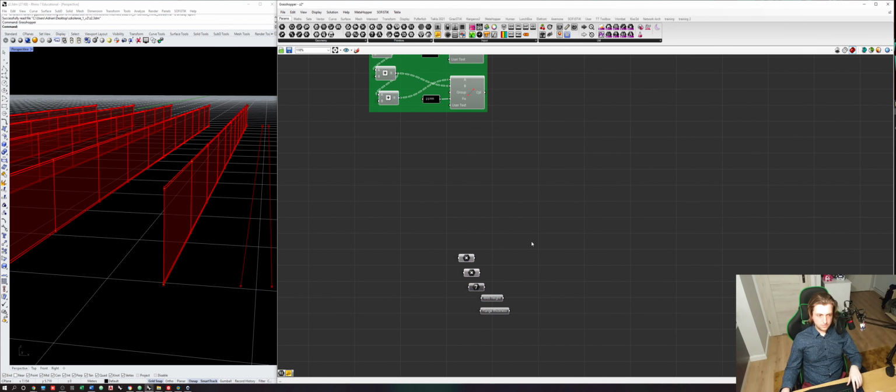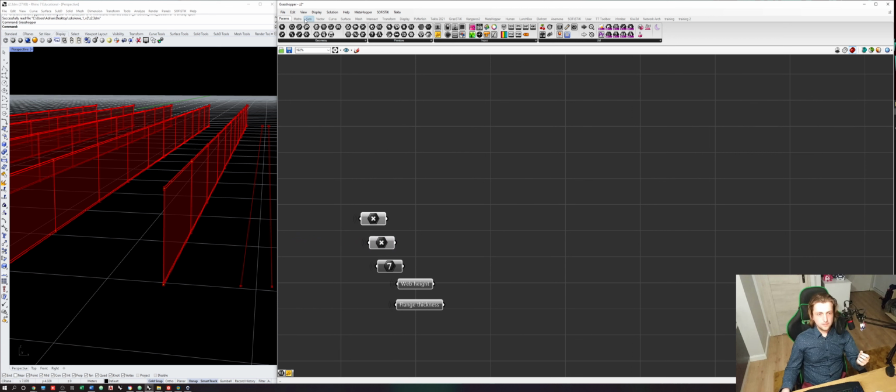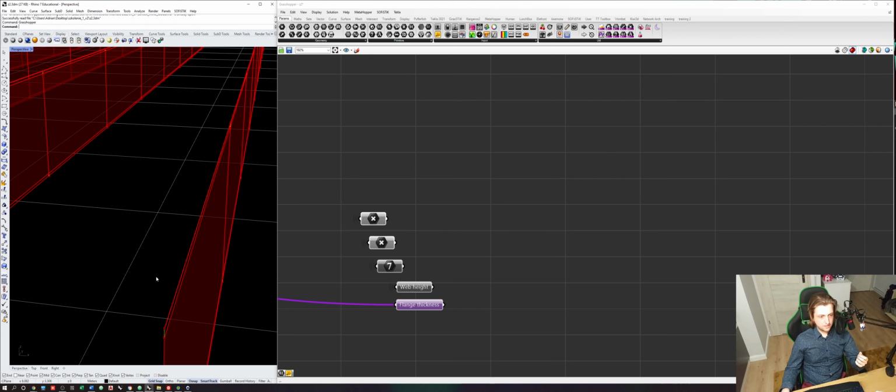Let's go down below and firstly move those points at the elevation or the height of the middle of the bottom flange height. So we have to create a vector, just collected these two data, the web height and the flange thickness, because here is a half of the flange thickness and here is another half of the flange thickness.